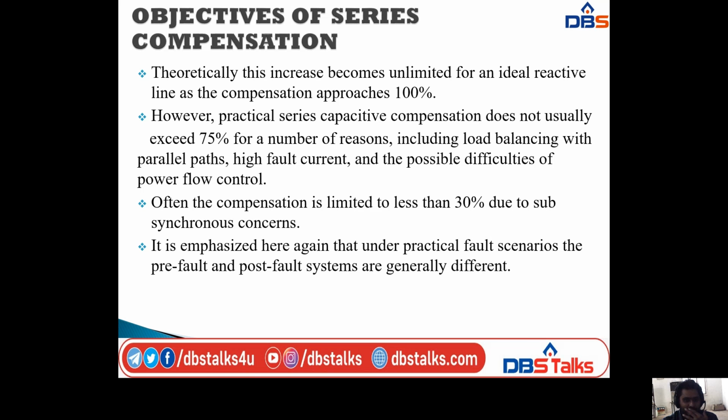Often the compensation is limited to less than 30% due to subsynchronous resonance.